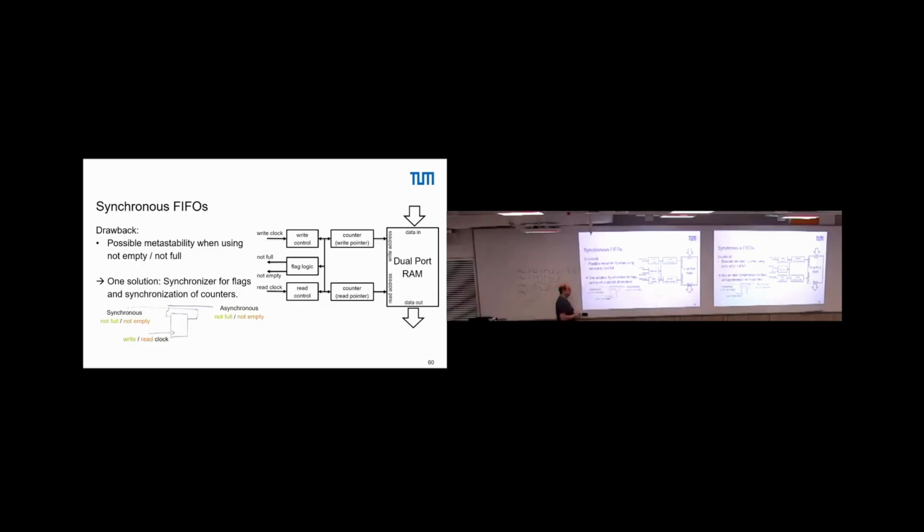But from here to here, there's analog behavior, right? So in between, you will see something like 110 because the first bit is already evaluated and the carry propagates here. 100, this is already evaluated, the carry is still in propagation. And then 000, so you have some other values in between which are different from this one and that one. And this can cause, by the comparison, that for a short time you have a peak here that is just wrong, right? So the comparison might get wrong.